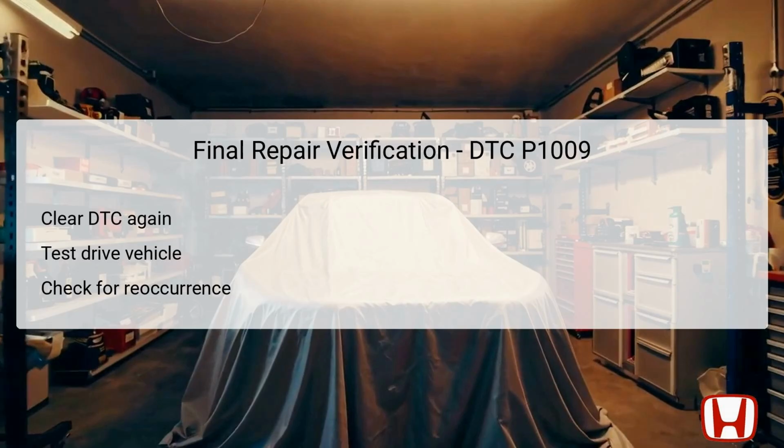Following this, it's crucial to take the vehicle for a test drive under various conditions to ensure that the VTC system is working correctly and that no trouble codes reappear. Pay attention to engine performance during the drive to determine if it behaves as expected. Lastly, after the test drive, perform one more scan with the HDS to check for the reoccurrence of DTC P1009 or any new DTCs. This final verification process plays a vital role in confirming the successful repair of the vehicle's VTC system.